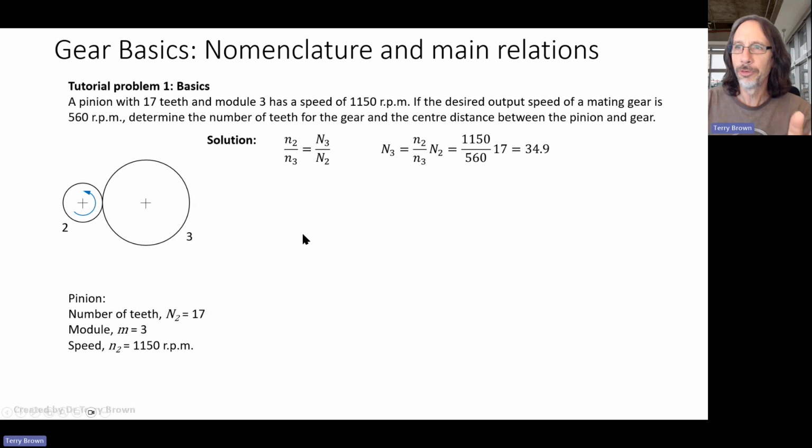I'm not going to go through that in this tutorial video, we talked about it in class. But if you look up hunting tooth or why you shouldn't use exact integer ratios, you can do that. Simply, the reason is that it evens out the wear. If you have an exact integer ratio, the same tooth comes in contact with the same other tooth on the other gear more often. Anyway, that's another decision you'll need to make from here.